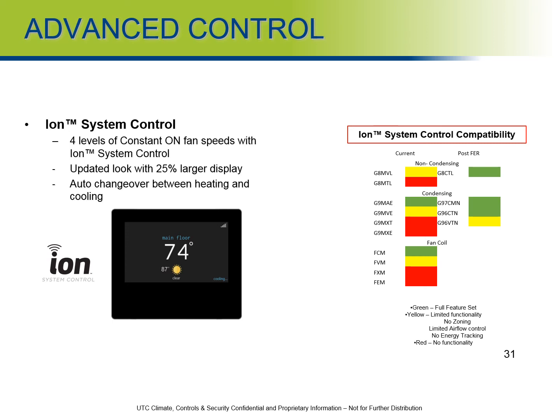Typically, in the past, specifically with PSC furnaces and even fixed constant torque furnaces, they only had one speed selection, which was typically high speed with the fan on position. But now with the addition of new control boards and communicating controls, they now have options of different speeds for the constant fan on position.